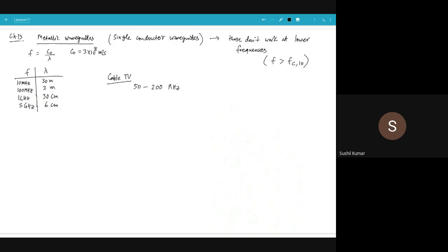Yes? The light itself is at a much higher frequency. It's just the digital signal that is at that frequency. Yes, exactly. That's called modulation. Your signal may be at a few megahertz, which means a few megabits per second if you convert it to a digital signal. But the light frequency itself, which is coming in the fiber, at 1.55 micron, is about 200 terahertz. This is megahertz, and that is around 200 terahertz.